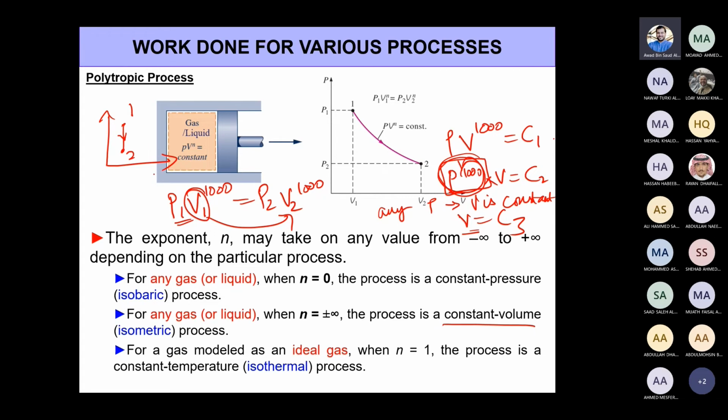If pressure at state 2 is smaller than pressure at state 1, let's say it's undergoing some sort of a process where the pressure is reducing. If you have a situation where the pressure is increasing, then it would still be a straight vertical line, but it could go up from 1 to 2, right? So based on whether it's going up or going down, the value for n would change. So plus or minus infinity indicates what is happening, right? So basically, how is the situation changing? If it is going up, it is plus infinity. No, if it's going up, it's minus infinity.